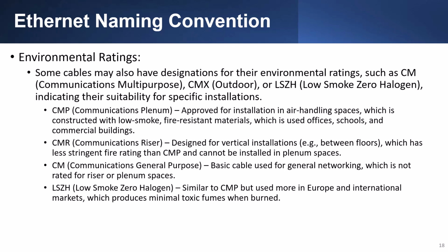Some cables may also have designations for environmental ratings, such as CM for communications multi-purpose, CMX for outdoors, and LSZH for low smoke, zero halogen, indicating their suitability for specific installations. Communications plenum, or CMP, is approved for installation in air handling spaces, which is constructed with low smoke, fire-resistant material, and is used in offices, schools, and commercial buildings.